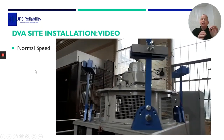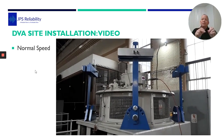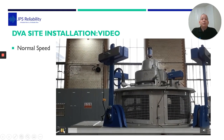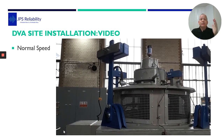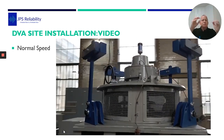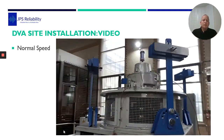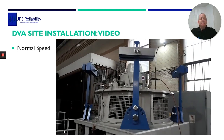So I designed these to be excited at the highest frequency we had on rotational speed. Now they're only good for one frequency. And on this unit, it ran at set point 3 the most, so we tuned it to set point 3 because this is the one they're running at 24/7, which is causing the fatigue. So as you see here now, at set point 3, they're exciting, and we were going around adjusting them, tweaking them, and they were all sort of interacting with each other, but they seem to be working.